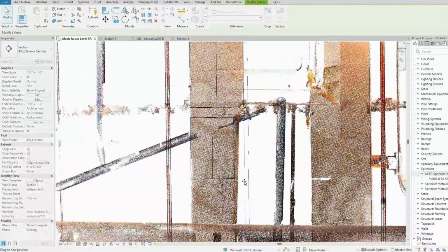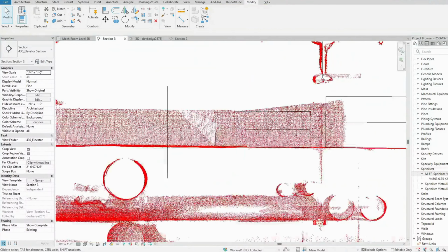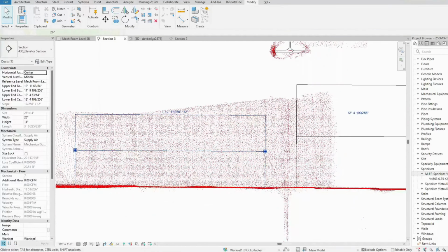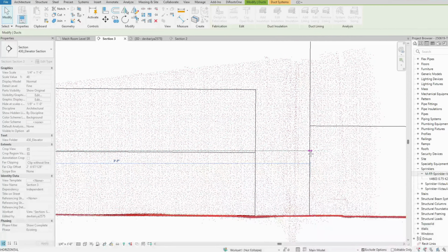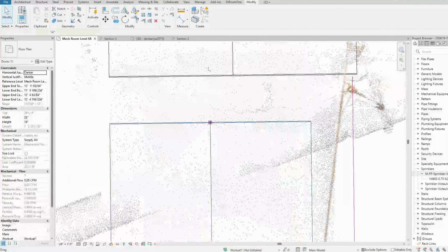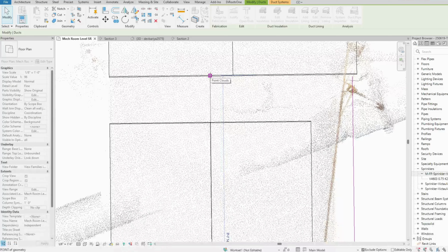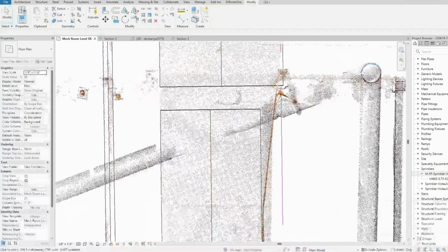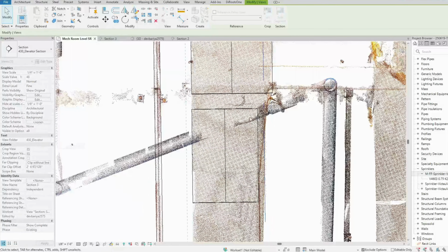Next, you need to choose the offset. The offset is the height at which your duct will be placed, measured from the current floor level. For example, if you want your duct to run just below the ceiling, you might set the offset to something like 2,700 mm, which is about 9 feet. This helps Revit understand how high above the floor your duct should be drawn.